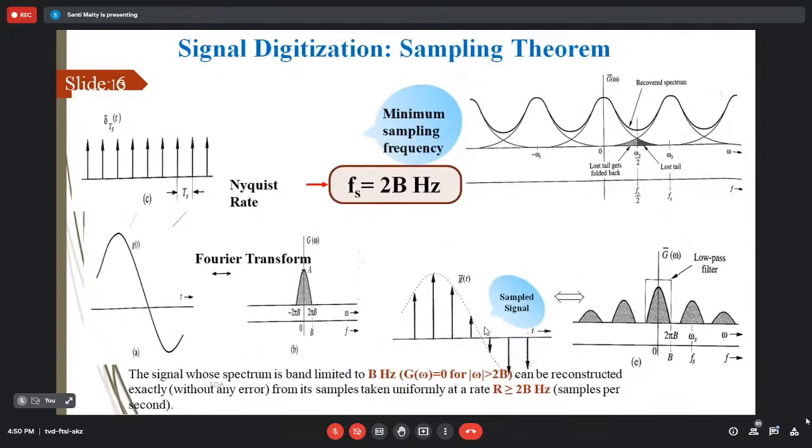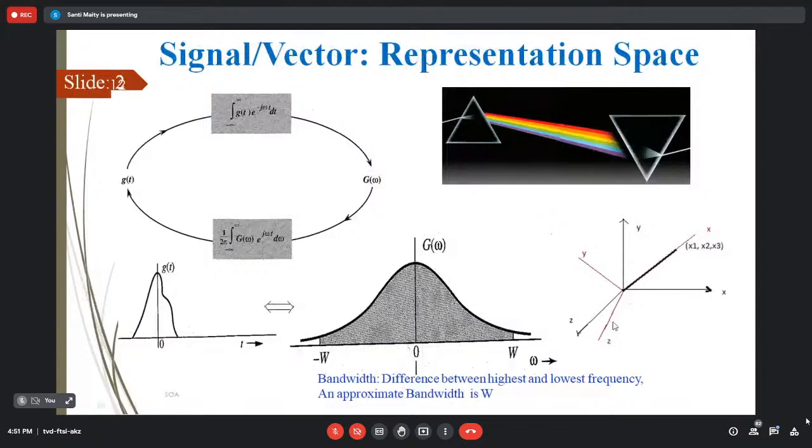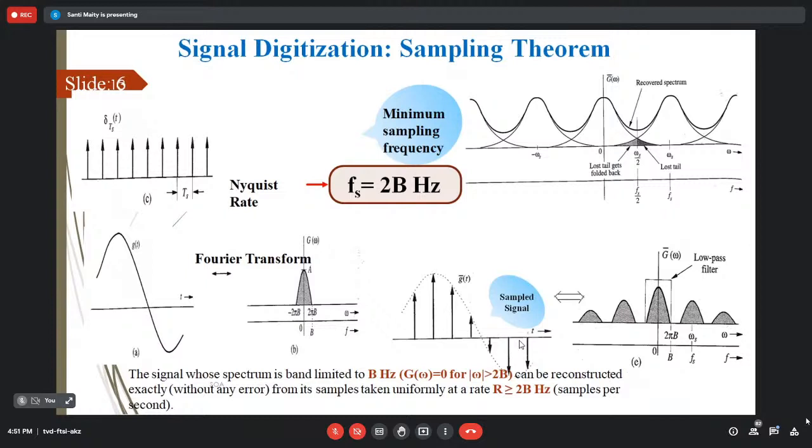Nyquist sampling theory says that sampling should be in terms of the bandwidth rate. But a real life signal theoretically has infinite bandwidth, yet it decays so fast that after a certain point the information rate is much lower than the bandwidth rate. So why don't we go for sampling at the information rate? It is possible.